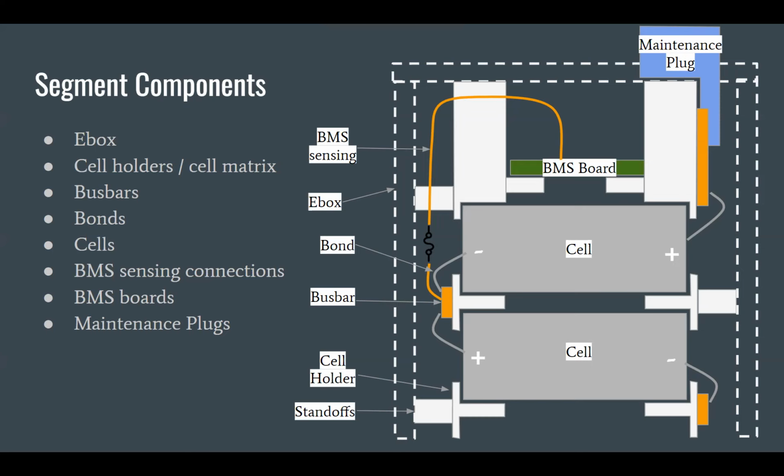the end. So yes, these current E-boxes are made out of polycarbonate. The final E-boxes are going to be made out of CPVC, which is high temperature PVC. The reasoning is because it is the only material that we could find in the thickness that we wanted on McMaster that also had the UL94-V0 flame rating that we needed.